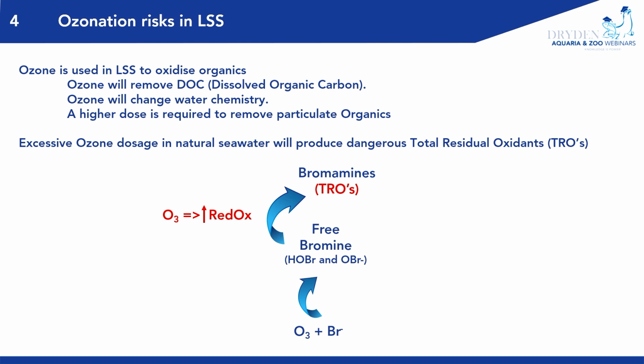And if a protein skimmer is managed correctly, with ozone managed correctly with the correct set point for the ORP control mechanism, then it is only being used as a flocculating agent, and it will help remove dissolved organics. Dissolved organics we can't remove in a particulate media filter. We can only remove them using ozone. The protein skimmer is actually a very good way. There are other ways, but for ozone in fish systems, the protein skimmer is the most efficient and most economical.